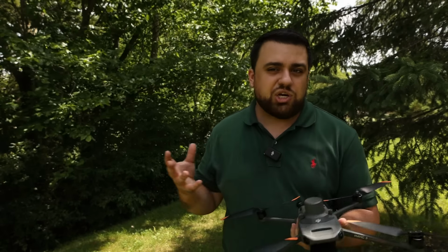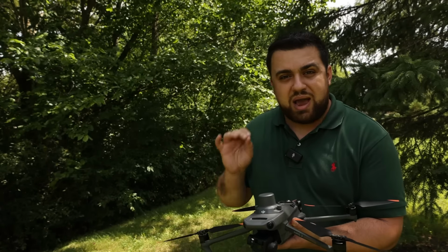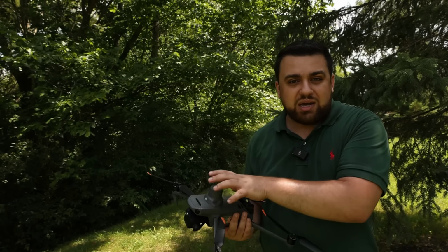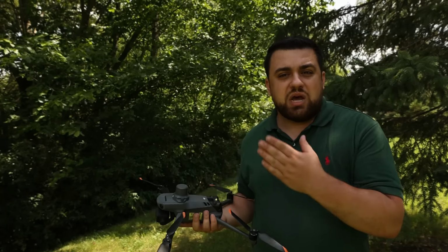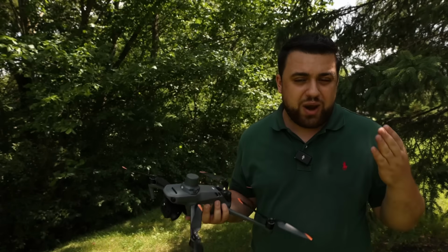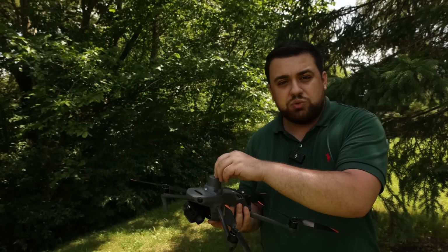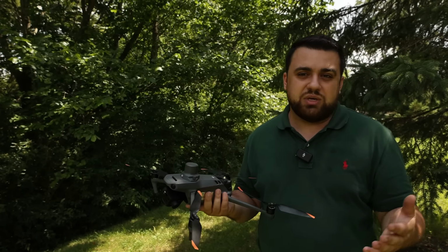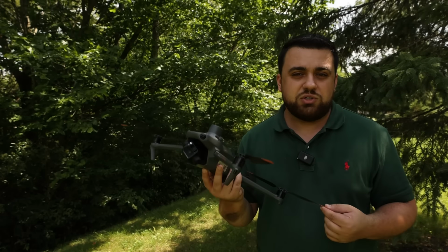The accuracy generally ranges between 3 and 5 meters, but with RTK, you can achieve centimeter level accuracy. This allows us to do drone surveying by achieving a higher level of accuracy when collecting the data in comparison to an entry-level drone. Now, real-time kinematic or RTK corrections is a method used to achieve real-time corrections to the drone's GPS position. So having this antenna allows us to do this, which is just one more reason why the Mavic 3 Enterprise is a great drone for survey mapping.